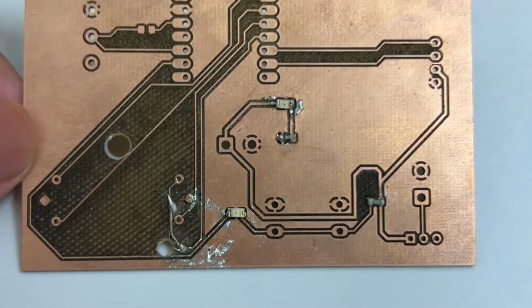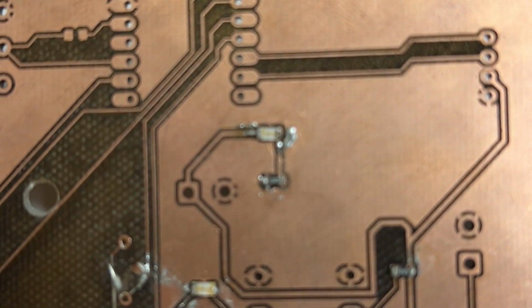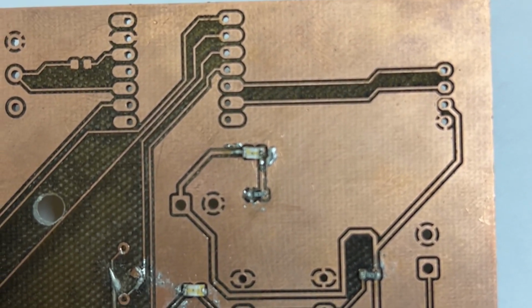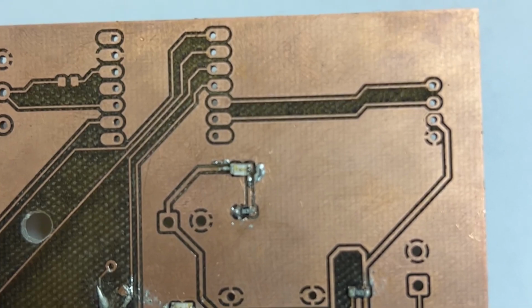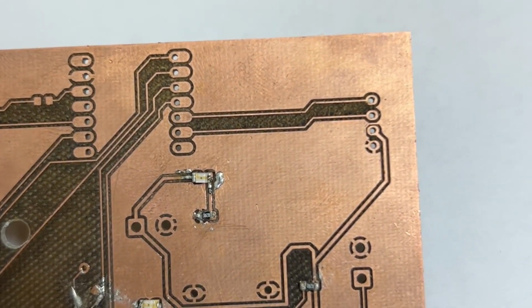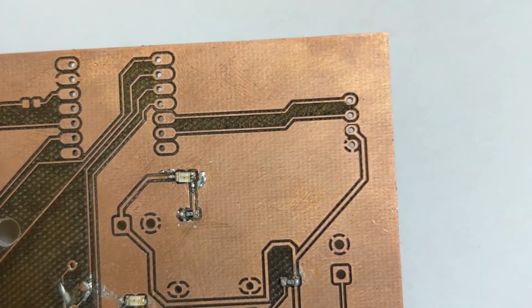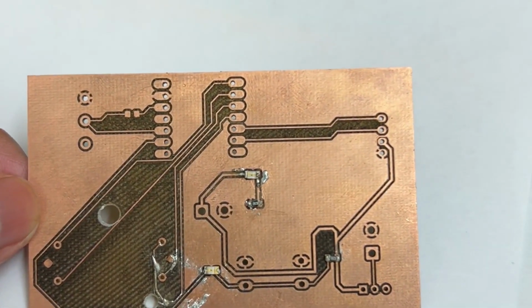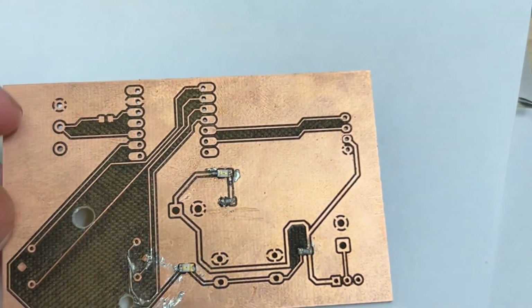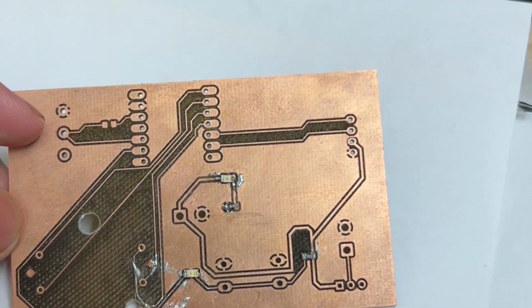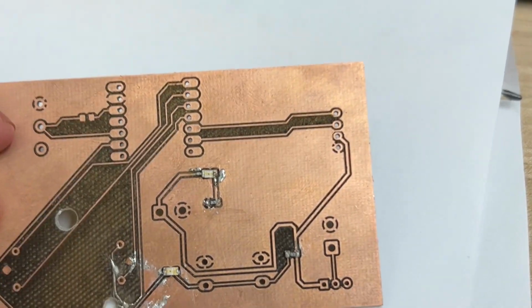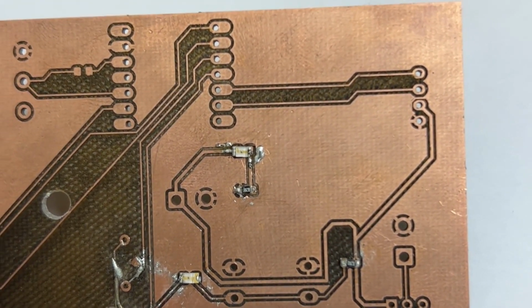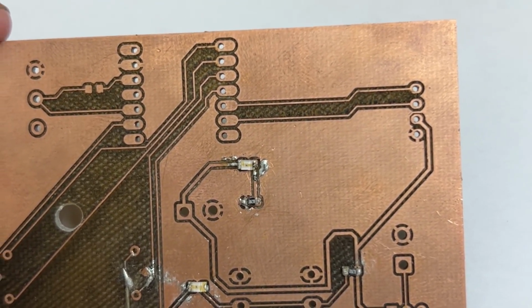The reason is that, as you can see here, these tracks connecting to the surface mount soldering pads are super tiny and thin, and also since I'm using the ground plate, which means all the rest of the plate with copper on it, not being lasered off, represents the ground node. So it makes these pads, especially the surface mount soldering pads, super difficult to be soldered,